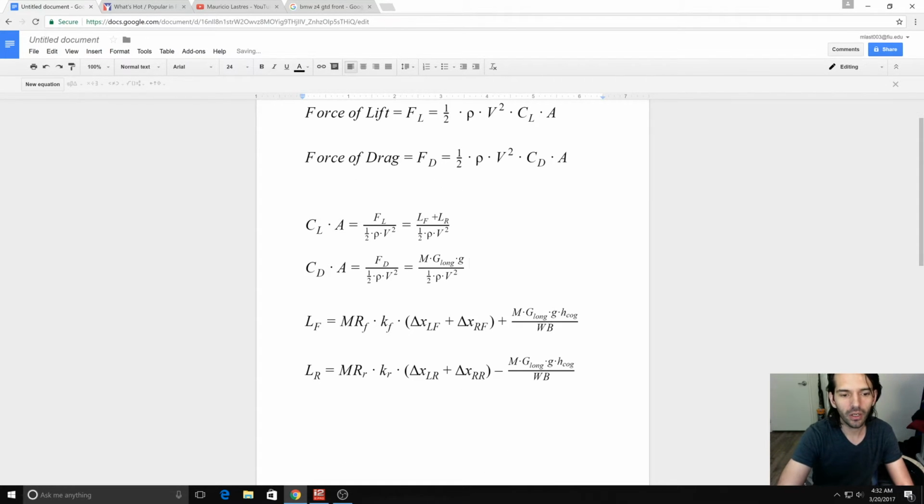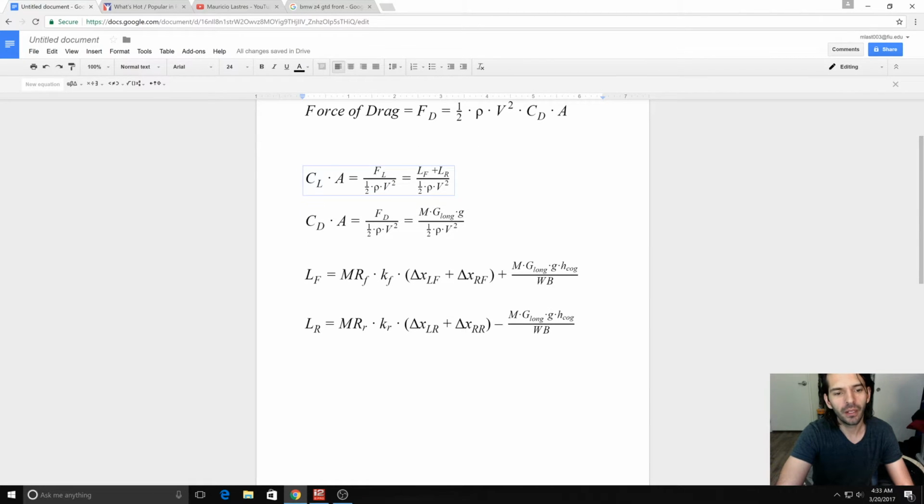So here are the equations for the load front that we have to insert into this function. The main one that you'll notice that's really important is MR, and you might ask, what's that? MR is the motion ratio of the suspension. We're basically going to be calculating downforce at the damper, and that's where I guess our suspension position sensors are, wherever that's located.